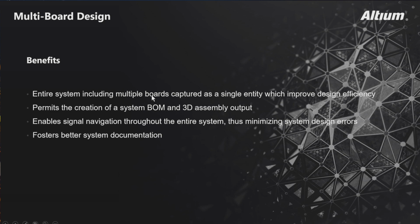One thing that I like this for, in my early days as an engineer, I designed this great multi-connector system, but what I didn't realize is two of the connectors were symmetrically reversed, and all the pins were swapped. I found that out in the lab, but something like this would correct that, or you build correct by construction. If you do this method, you can build up so that all of your signaling is verified as you create this top level project. So that would have been nice to have years ago.